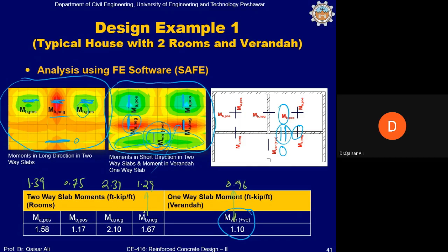So all these values are closer to each other. There will be some difference, of course, because the slab coefficient method is an approximate method, but the values are closer to each other. Okay, but if you take 1.5, that is the moment coming at this support from the one-way slab analysis, it is not closer to this value, so it means that the maximum of these two will be picked for the design. Okay, clear? जी सर. इसमें कोई क्वेश्चन है? एनी क्वेश्चन?